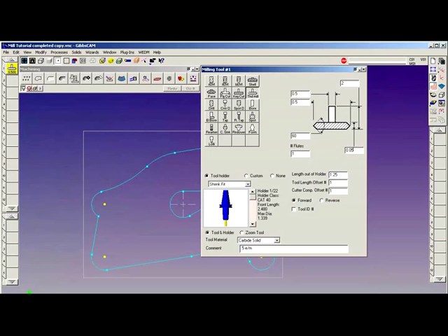This is defining a single point thread cutter. When thread milling in GibbsCAM, we are defining the lowest tooth or cutting surface on the cutter. In the case of a thread hob or an insertable thread hob, sometimes you can generate the entire thread with just one revolution. So what you do is you base the bottom thread of your thread hob at the start of your thread, typically the bottom, and you come up 1, maybe 2 revolutions, and the insert or the hob will form the rest of the thread.